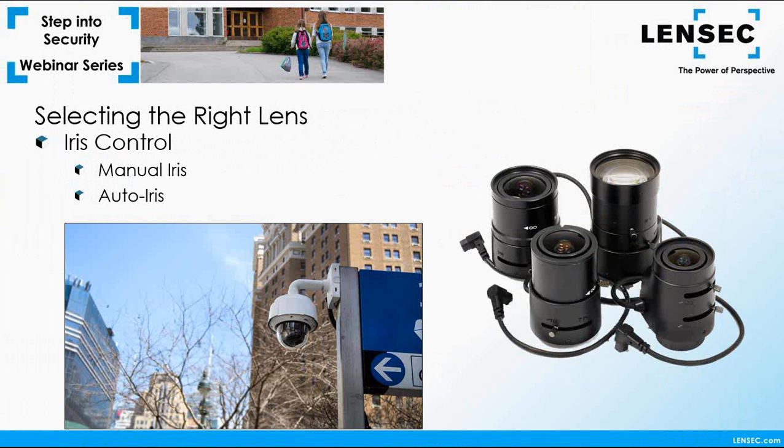With rapidly changing lighting conditions such as clouds moving across the sun, the auto iris can react much more quickly to adjust the image. This helps to achieve the proper exposure faster than the automatic gain control on the camera can react. When you're deploying a camera in an outdoor environment, it's wise to use an auto iris lens. It avoids lagging exposure due to a slow automatic gain control.